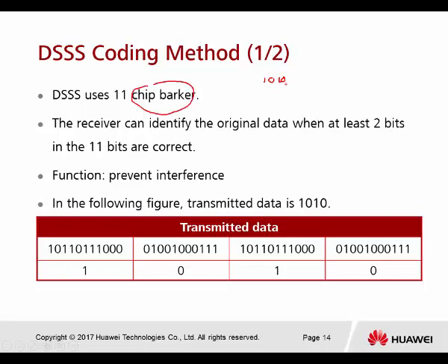When we transmit this information, it is binary. After doing the modulation and transmitting it, it becomes a certain radio wave, and this radio wave carries the bit information, based on what kind of modulation you use. If you still remember, we have AM, PM, and also FM modulation, 3 different types of modulation. Every modulation is done bit by bit. So if one of the bits gets interference from another source, maybe the information becomes inaccurate.